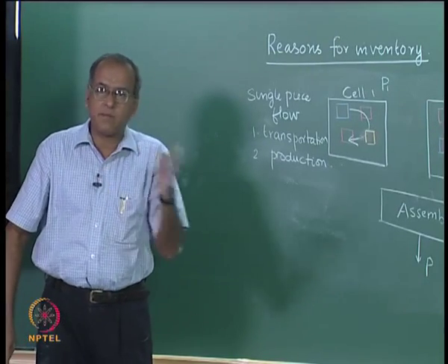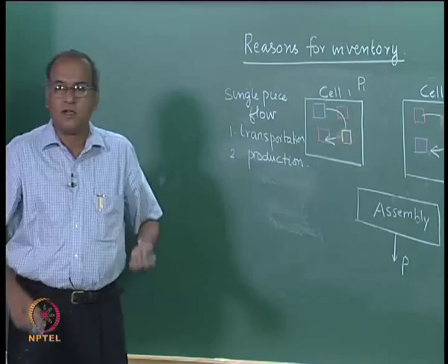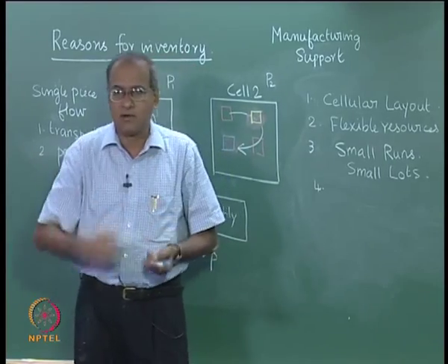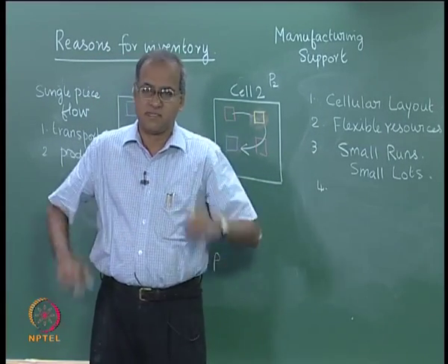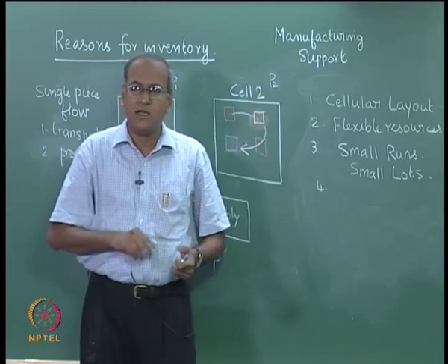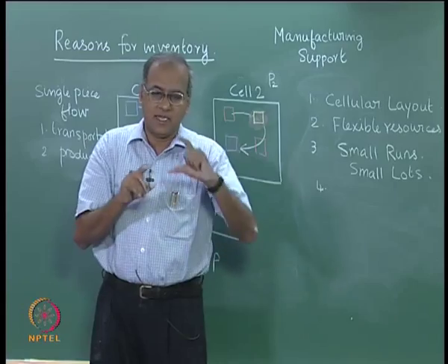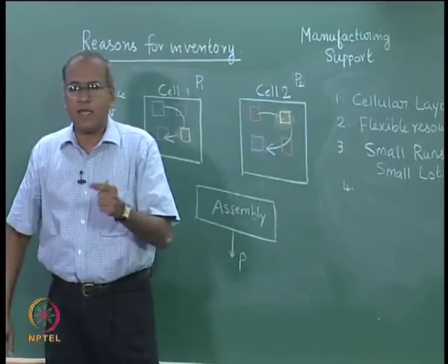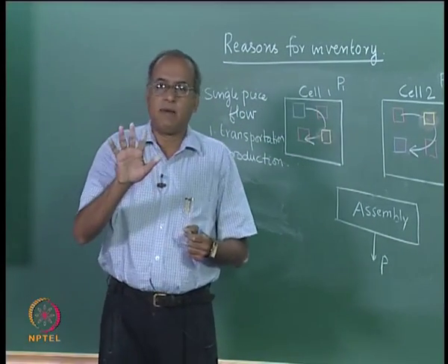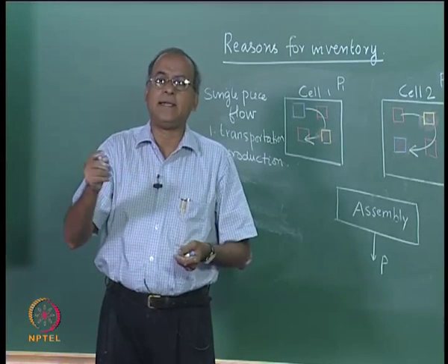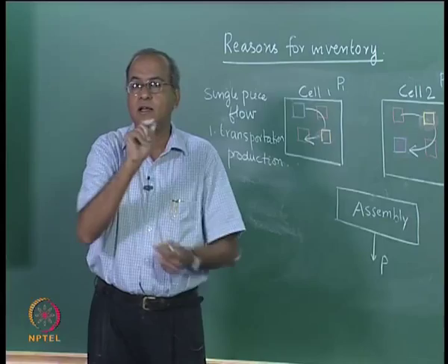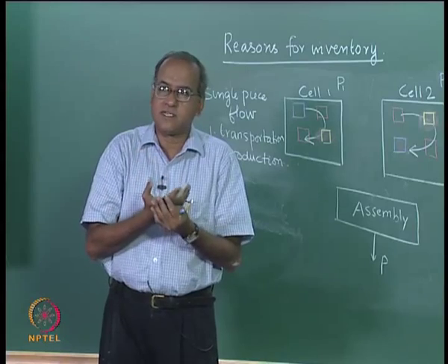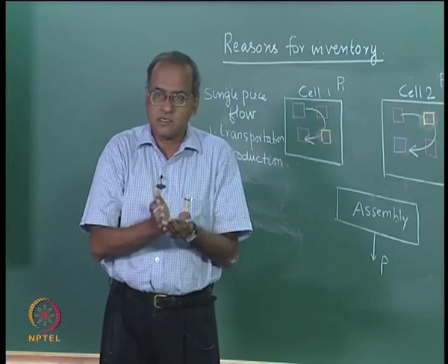Now, when we did that example in a previous lecture, we also found out that when we did production batches of 5 instead of production batches of 10, the total time to produce was increasing. The reason for the increase was, if we were making 4 parts and each in a batch of 10, there would be 3 or 4 changeovers. If we start making them in 8 batches, each with a batch size of 5, there would be 7 or 8 changeovers depending on whether we want to come back to the starting part. So, the number of changeovers increases.